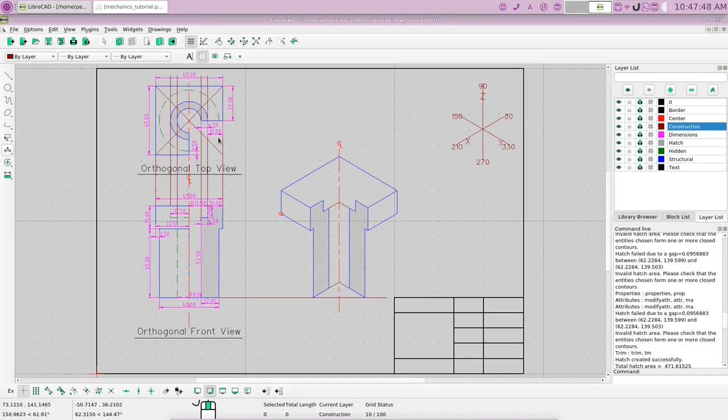Okay, from free snap, let's go with an angular line, and let's make it 25 units. Okay, and 30 degrees is fine. Let's put it somewhere in here, just spare space. Okay, and let's change that to 150 degrees. And let's put the snap on end on. And let's snap here, and let's snap here. Now, let's go back to 30 degrees. And let's close that up.